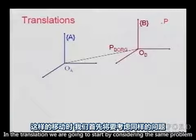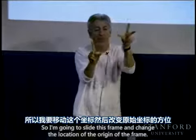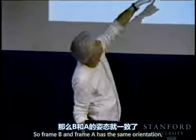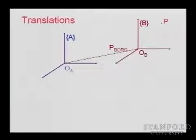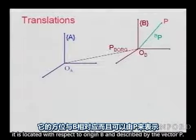In the translation, we are going to start by considering the same problem, but while maintaining the same orientation of the frame. So I'm going to slide this frame and change the location of the origin of the frame. So frame B and frame A have the same orientation, and we're going just to move along the direction of the vector P. So if we have a point in space, it is located with respect to origin B and described by the vector P.